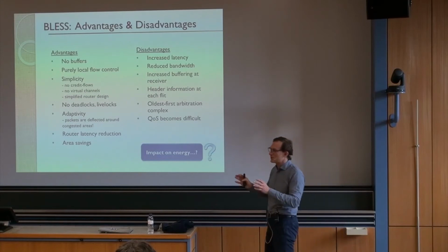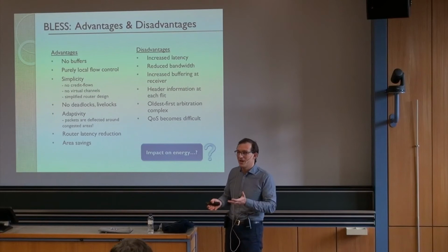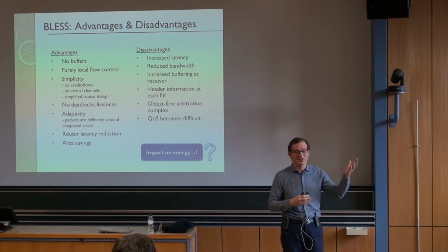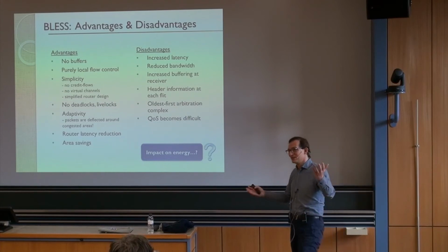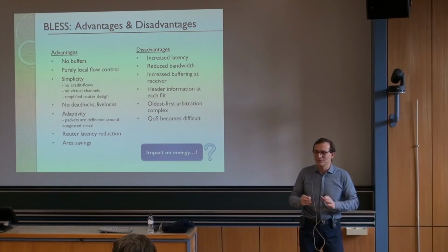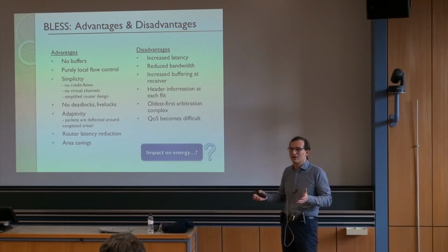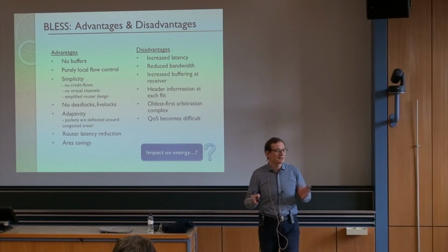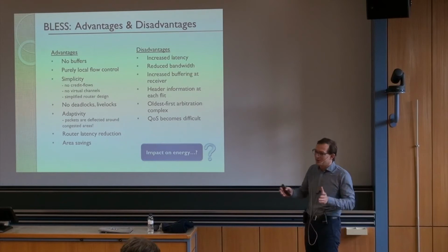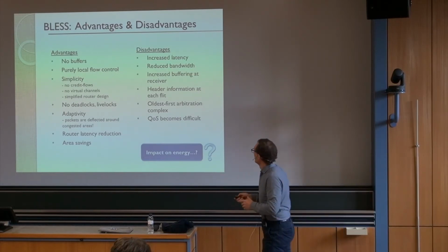Now there's also the interesting question there, what fraction of your packets are single-flit packets and multi-flit packets, right? Control packets are usually single-flit packets, unless you have a really narrow network. Usually they're not really narrow on chip, because your control packet doesn't need to provide more information than, let's say, 8 bytes, right? You can encode a lot of information in 8 bytes or 32 bytes. But your data packets are usually the ones that are longer.